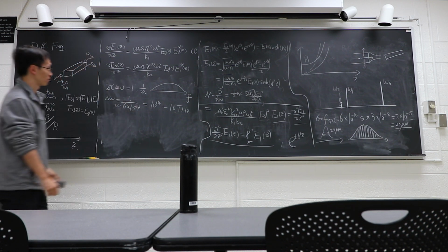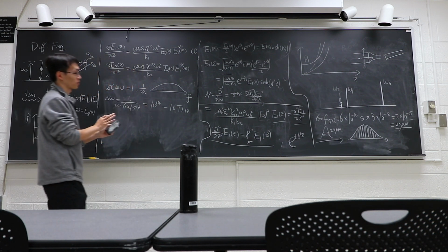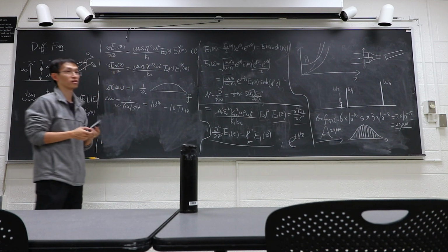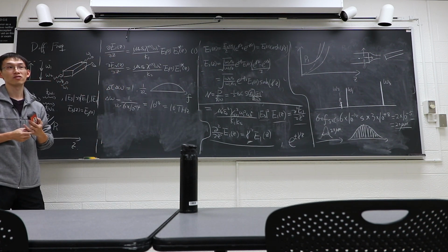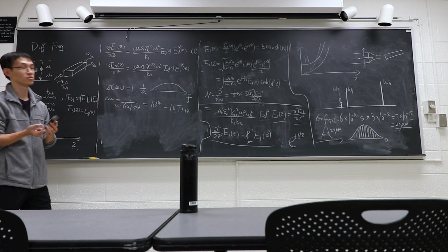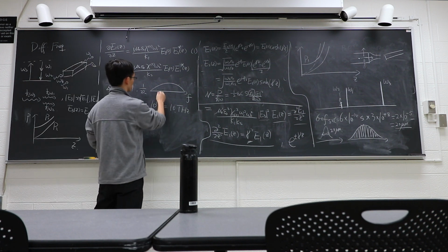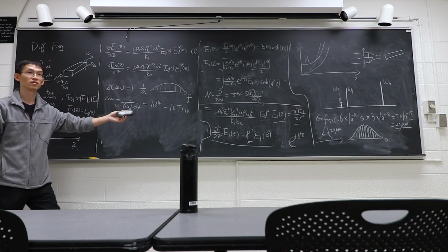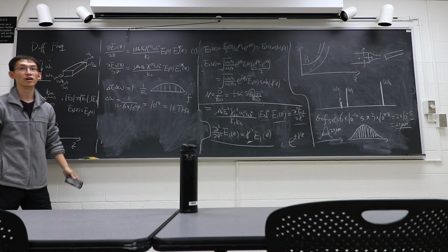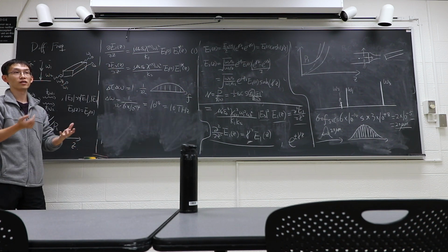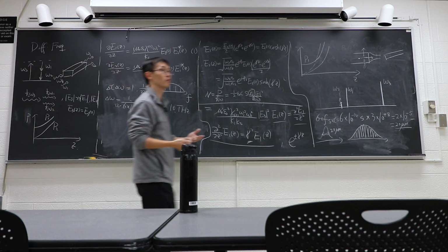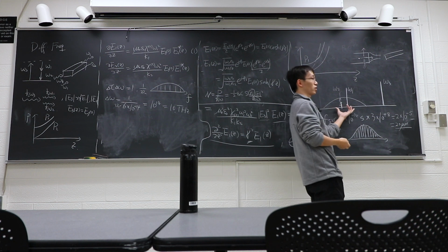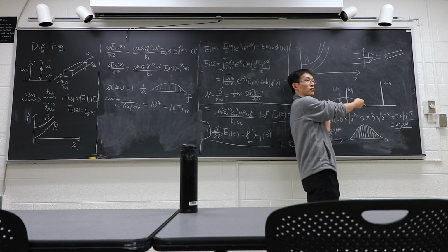But from our experiment, we can generate pulses around 100 femtosecond width from a chip-based device, very small. And then in frequency domain, they look like this, 10 terahertz wide. So if you want to amplify it, you have to have your parametric gain very broadband.